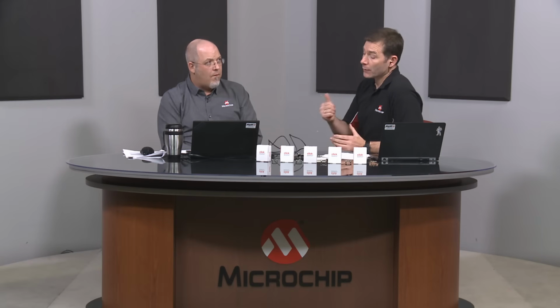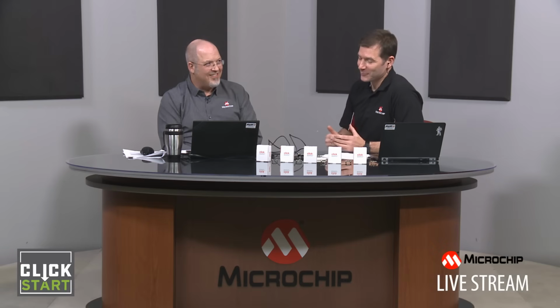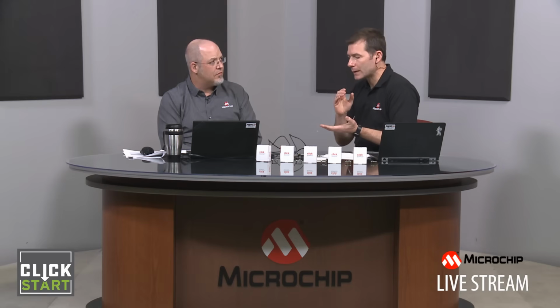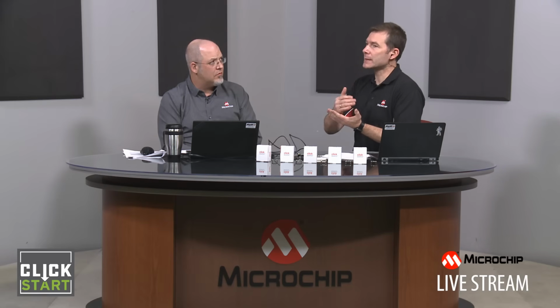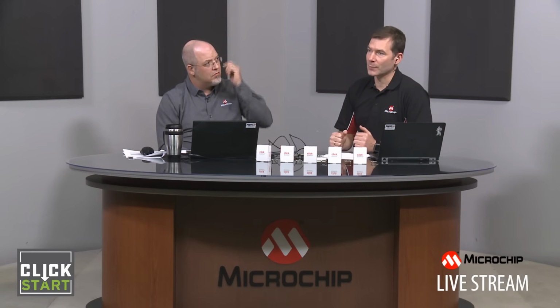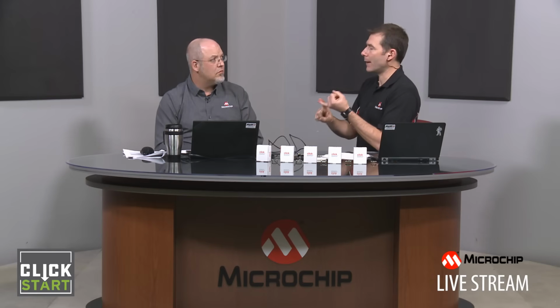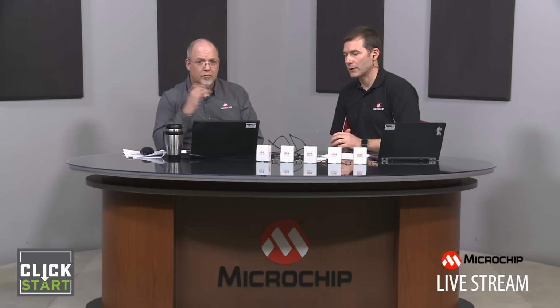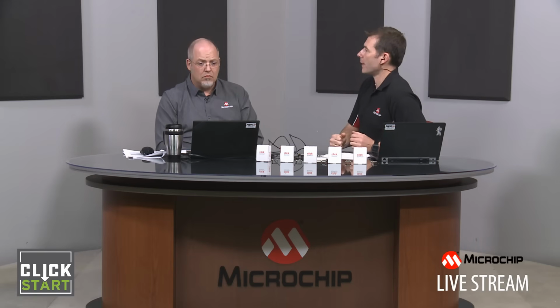Another good thing about IAR that I just have to mention now that we have the opportunity is that debugging capabilities are really, really good. While in some compilers, if you increase your optimization, that decreases your ability to do debugging. Right. But in IAR, you can actually turn up the optimization quite high before debugging starts to become an issue. Very cool. And IAR has a Kickstart version. So if you want to experiment with that, you can either have the 4K limited version, or you can have the time limited version instead. So that's a good thing. But we're going to use Studio today.